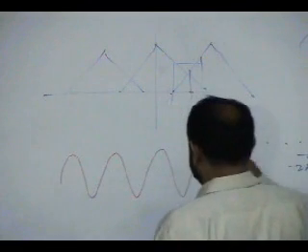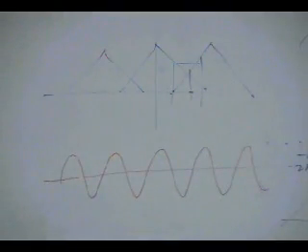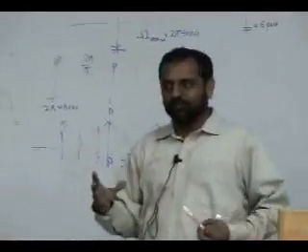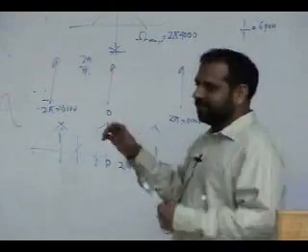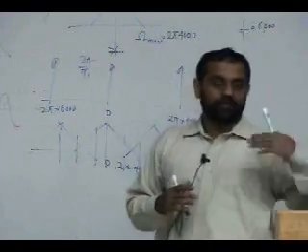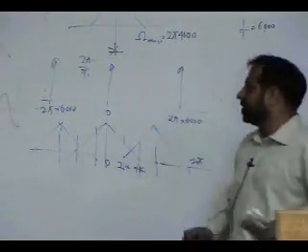Like if I have a frequency like this, okay, and I don't have any slow moving component, I can really sample it at any rate. This sinusoid will map to a slower frequency for sure. You will still get a sinusoid. It will be a slowly moving sinusoid. It won't be this, but it will be there. It will not corrupt anything if something is already there. Okay? This is really used a lot, and we have used it a lot.